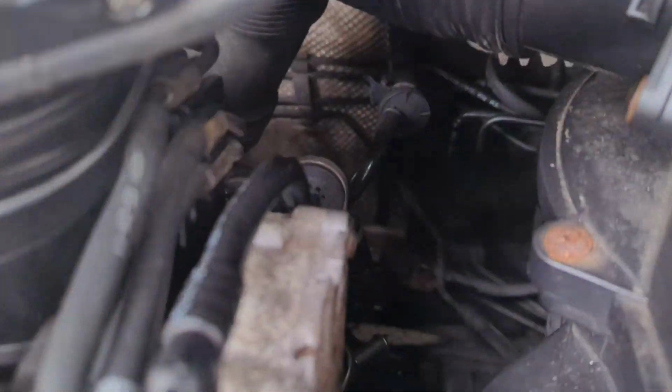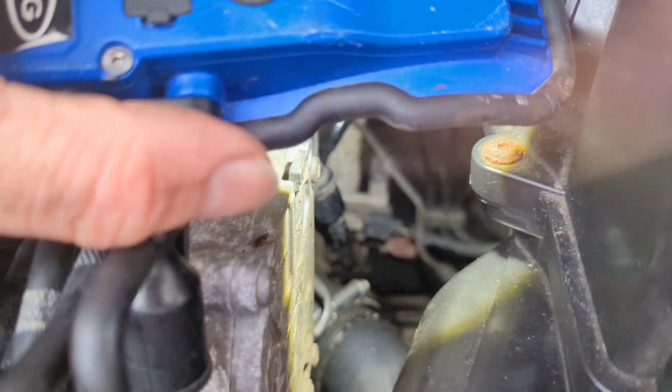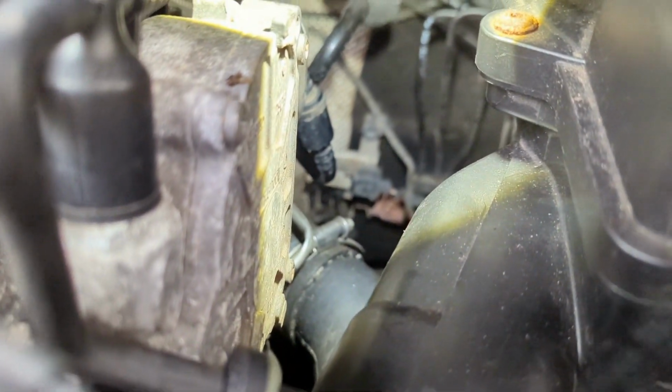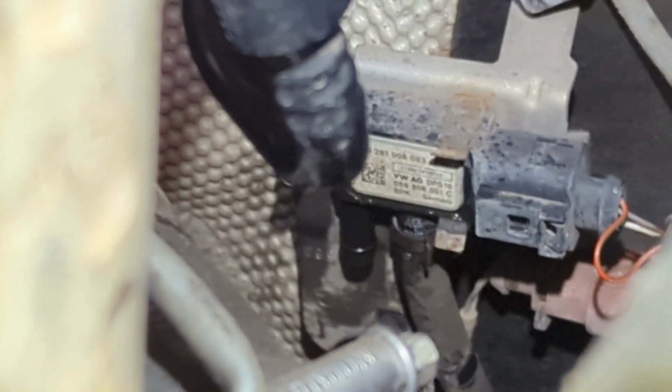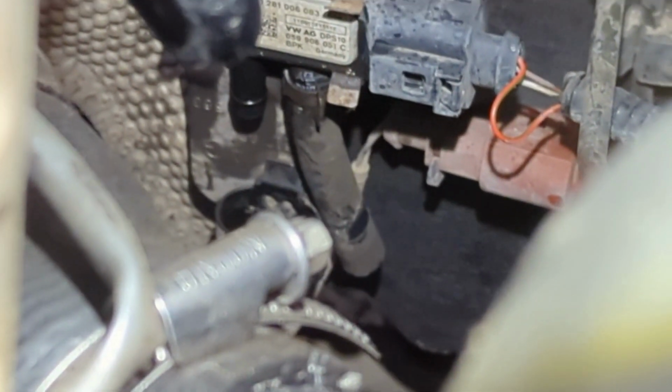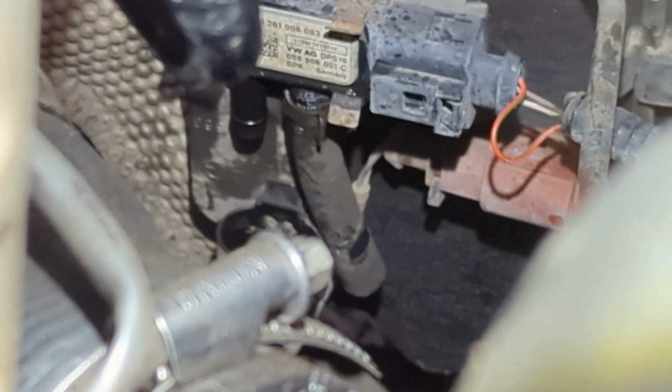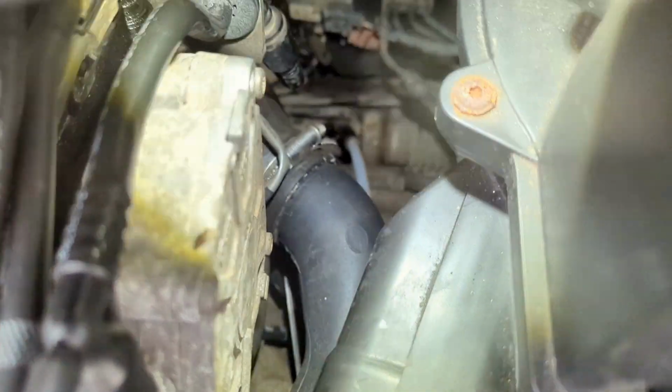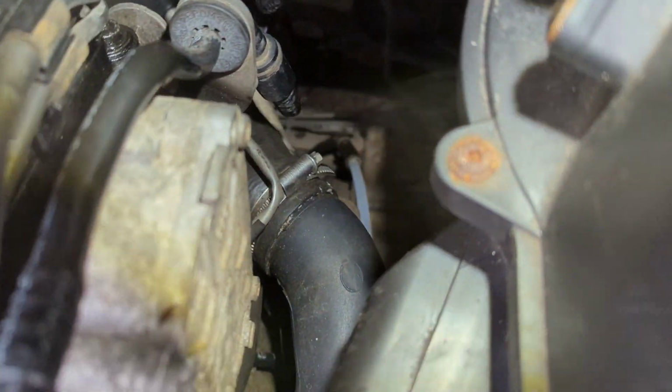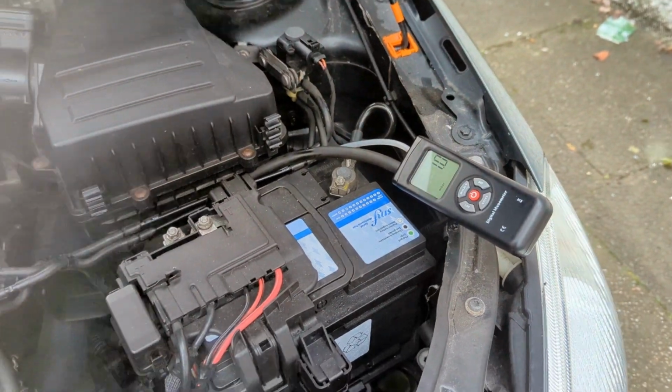So the pressure sensor on this one is down here. There, there's 2 pipes. The one on the left is what I've removed. That goes to the exhaust itself, pre-DPF. On some cars the second pipe will be post-DPF. This one is just referencing atmosphere, and then I am piped in here, this white translucent pipe, up to a manometer here. So let's start it up.